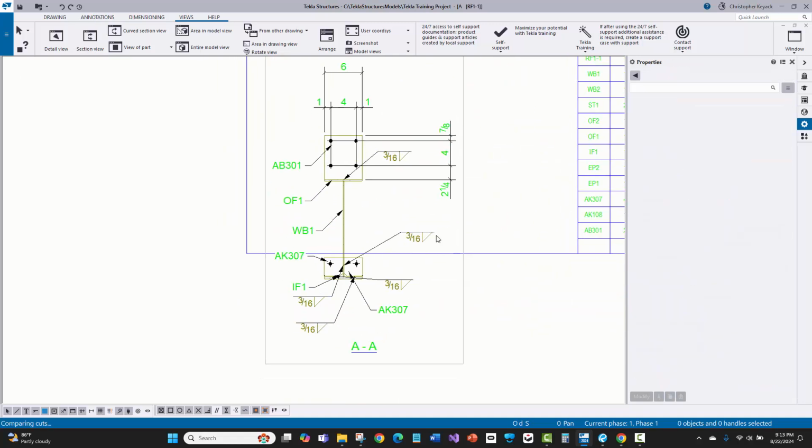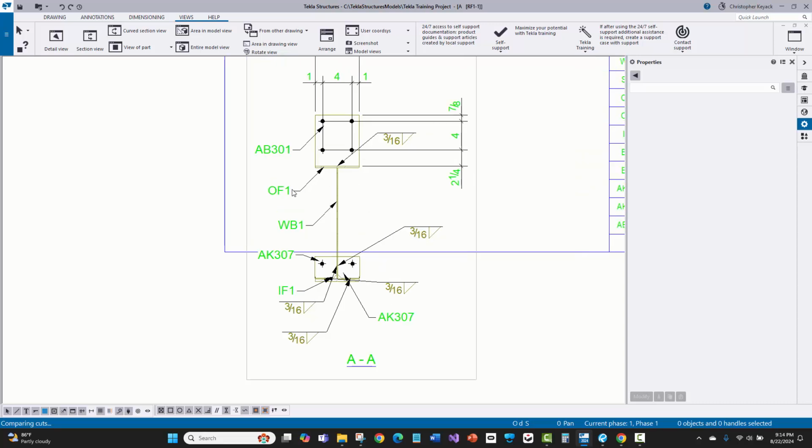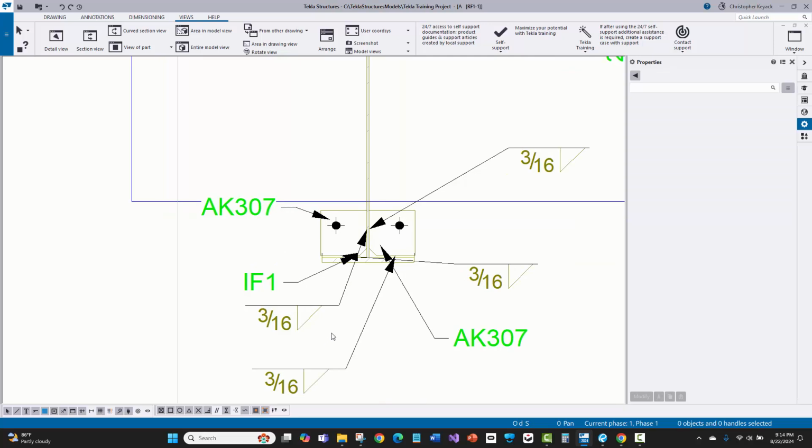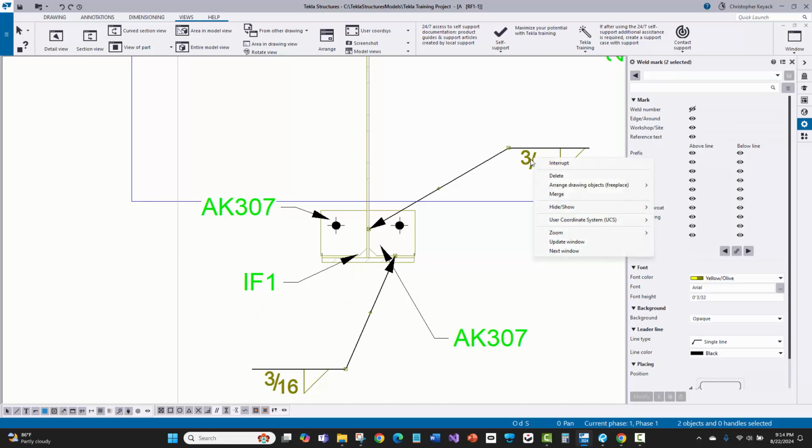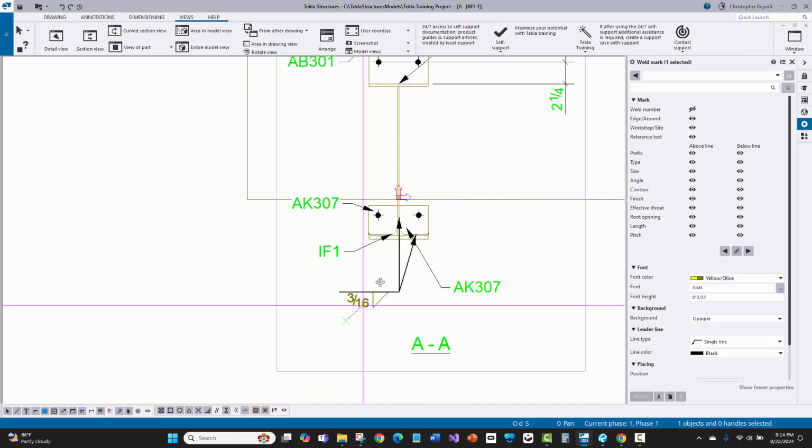Now, here I've got some welds basically shown because this pretty much matches what you see on a lot of MBS drawings. So I'm just going to take these off. But if you just had weld standards, you could delete those welds off there if you don't need to see them. So here, if I've got welds on both sides, I don't need to see that, so I'll just delete those. These are exactly the same welds, so I'll right click and merge those and just drag those up.